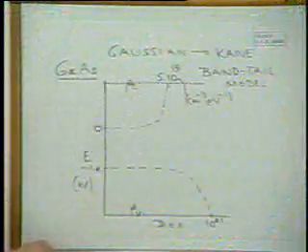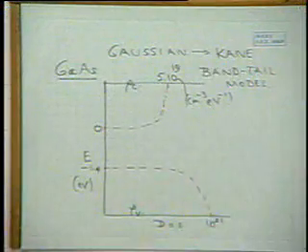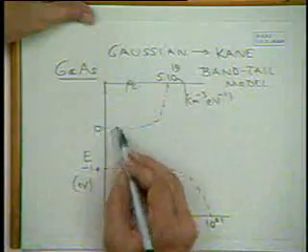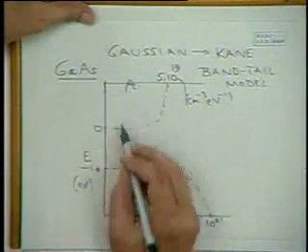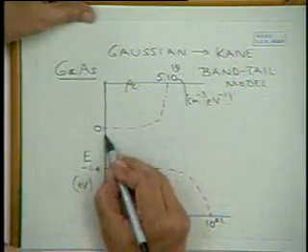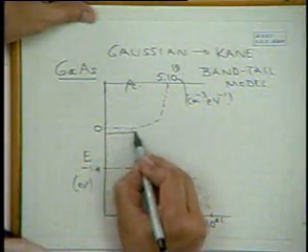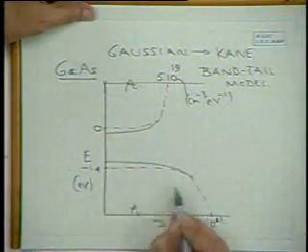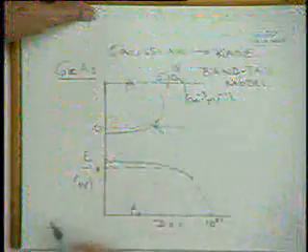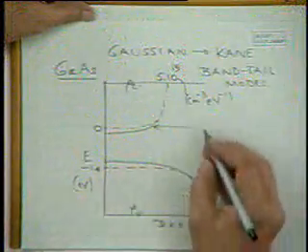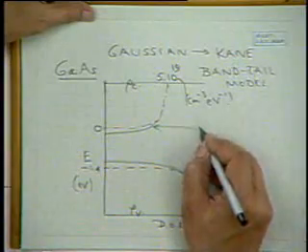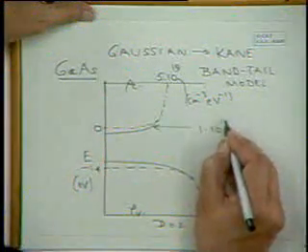Now physically, the material that we are dealing with in lasers is not lightly doped. It is much more strongly doped. Then the density of states is no longer like this. There is this band tailing effect. What does band tailing mean? Band tailing means that the effect of the perturbation is to shift the conduction band down like that and the valence band up. And the shifting depends upon the concentration, it's concentration dependent. So this one, say, is for 10^18 per centimeter cube.